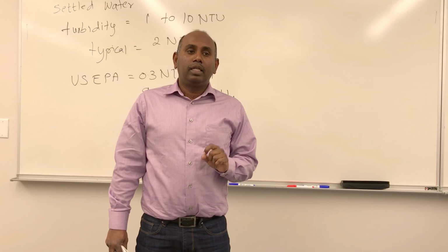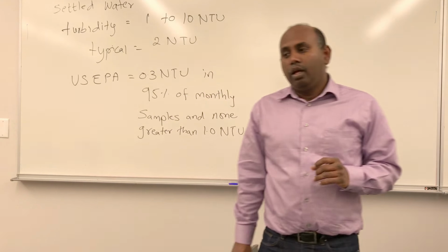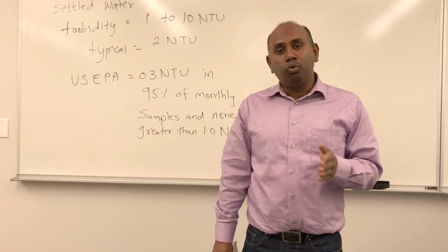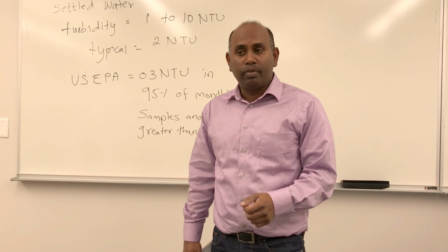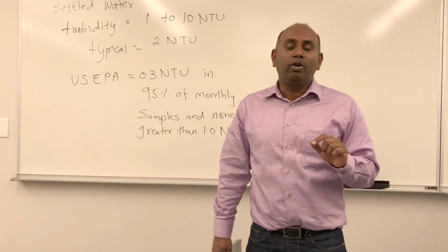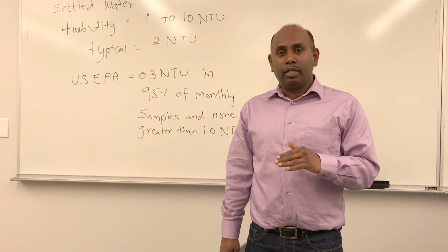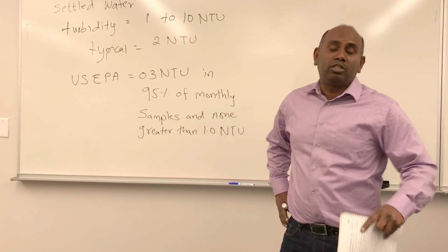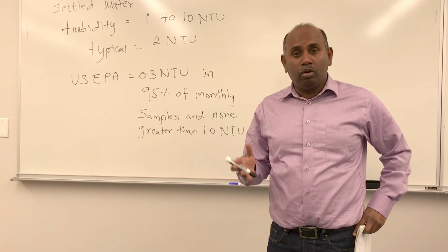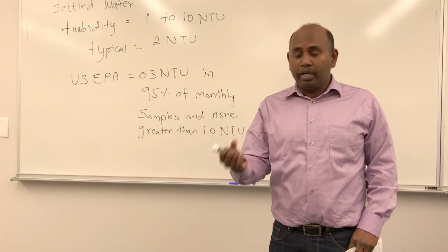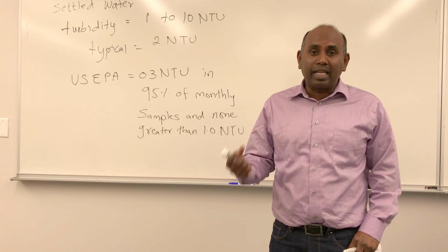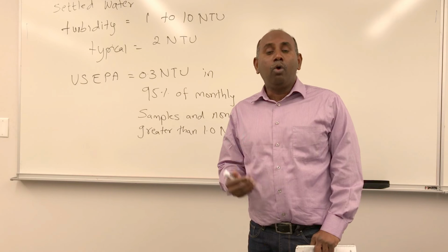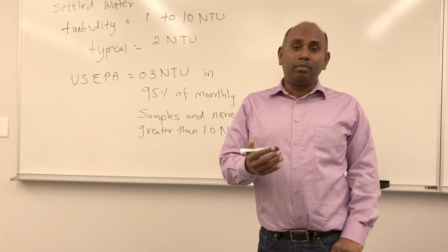We're going to look at granular filtration today. What we've seen so far in the classes, we started talking about drinking water treatment focused on surface water. Within surface water, our concern was removing suspended particles that are floating in water. We looked at the reason why particles are stable in water. Particles stay in suspension because of particle stability due to surface charge, electrical double layer, zeta potential, and we also looked at how we can add a coagulant and destabilize those particles.